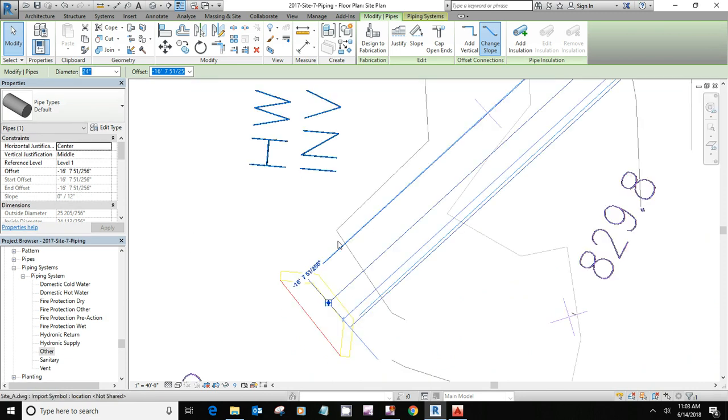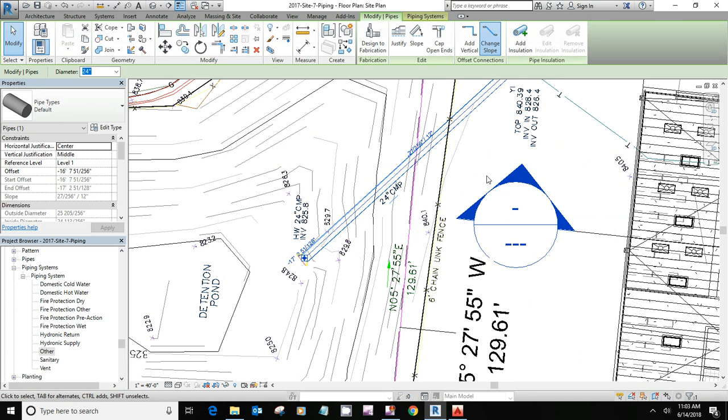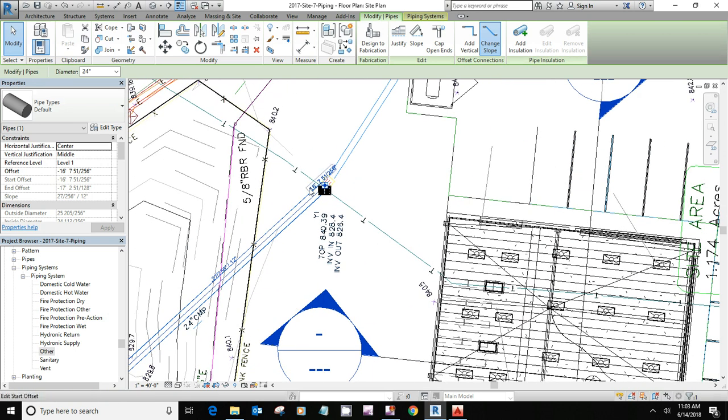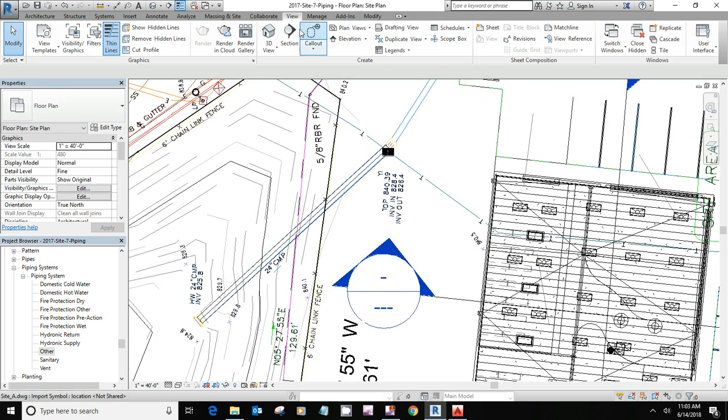And I selected it. I can get my offset right there, so I can put in my lower offset of minus 17.2 feet. And okay, so it converts it over to inches. Now let's put us in a section view.